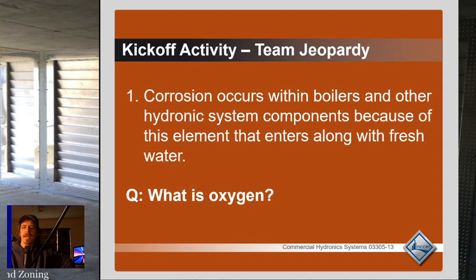So you basically got two options. You make it out of a really good piping system that will not corrode as easily, so use less iron components, use more brass, copper, stainless steel, things like that, or use all steel components, but try and do a very good job from the beginning so that it doesn't need to be opened up very often. Put a lot of valves and things that need to be serviced so you don't have to drain a lot of the system to make certain repairs. All these things are extremely important when it comes to hydronic systems, so it's something to keep in mind as you're piping it.